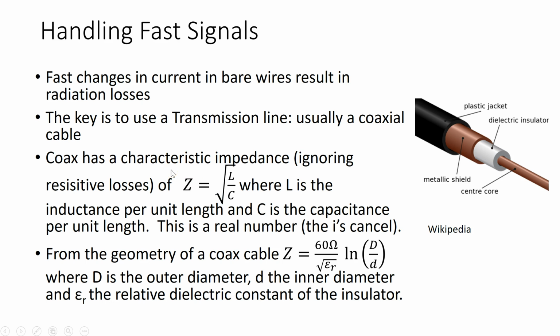The reason is that dipoles that radiate effectively have an intrinsic resistance from electromagnetic theory of about 75 ohms, and so a 50 or 75 ohm cable is pretty effective for power transfer into a radiating dipole. Remember the little theorem we proved that when source impedance matches load impedance, maximum transfer occurs.